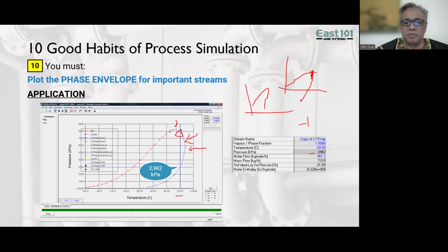So because of that, you've got this bulging. This point no longer denotes the maximum temperature and pressure of your system. Instead, your critical point has split into a maximum pressure point, or cricondenbar, and a maximum temperature point, or cricondentherm. So that causes this bulging behavior here.